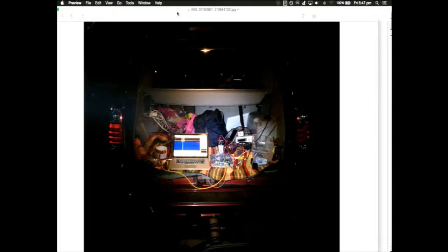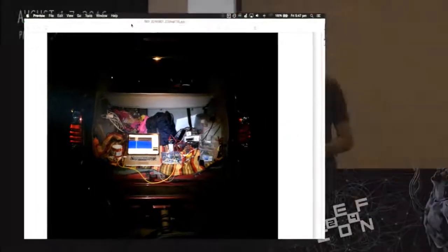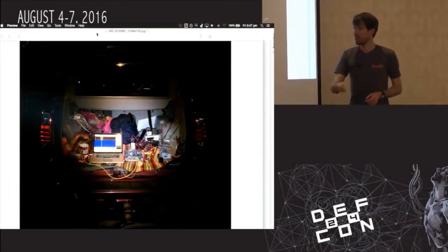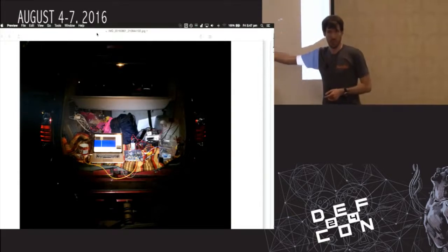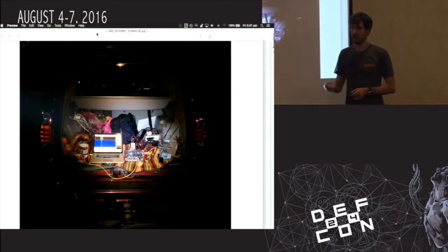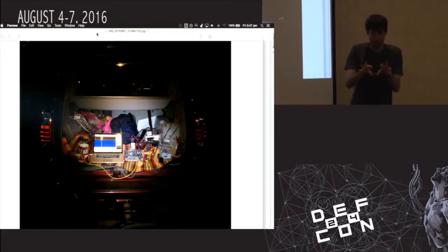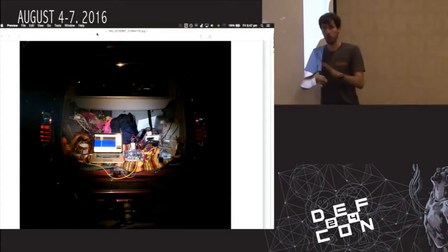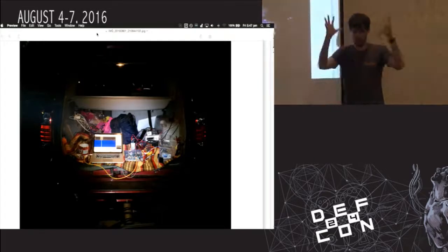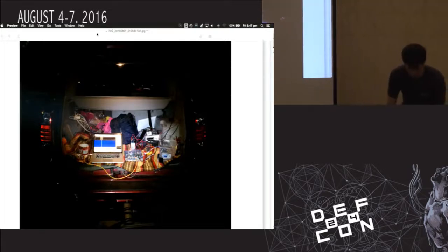So then we also got a 110 inverter to power off the car to attempt to charge the laptops with. As soon as we plug that in, you can't just verify and determine what's going on just by plugging it in. You actually have to put load on those switch mode supplies. So you plug it in, nothing happens. And when you actually plug in the laptop to charge, then everything disappears into the noise.